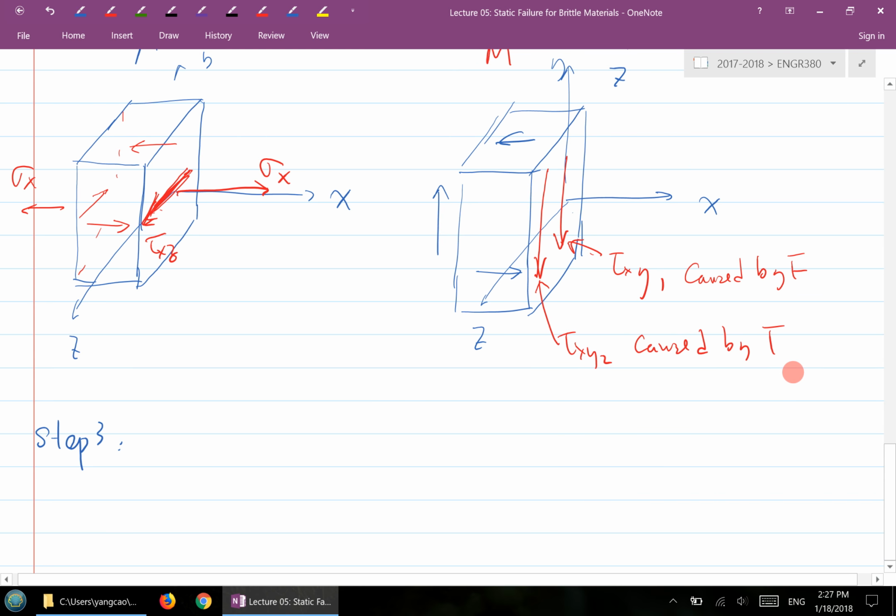Why are we drawing the 3D stress? Very good point. So I'm drawing a cube here, but you're absolutely right. Your observation is that this is essentially a planar state of stress, isn't it? Remember in the previous lecture we mentioned, what we normally look at is a planar state of stress because the loading gives us a planar state of stress. However, we are actually going to put this in 3D, because we also consider the 3 principal normal stresses, which is in 3D, right?